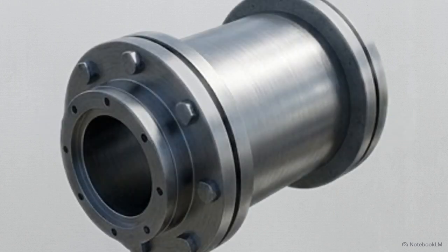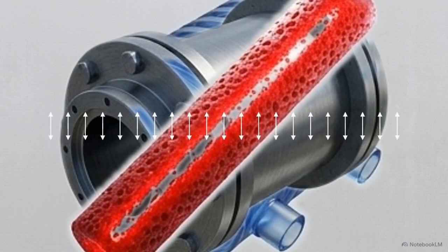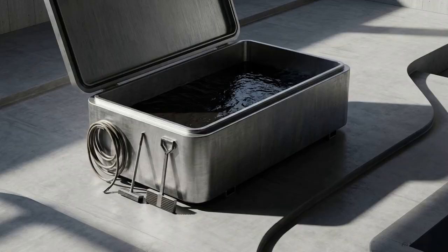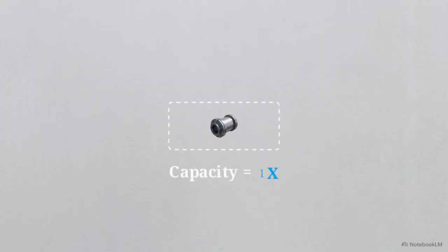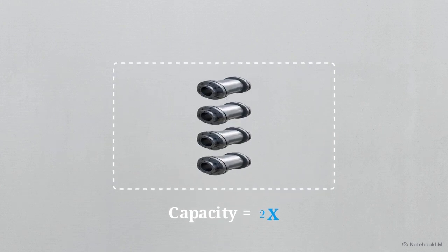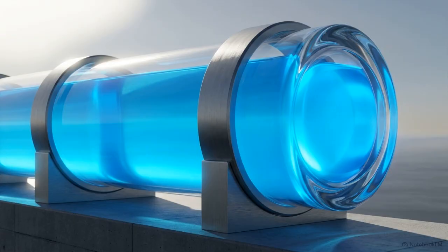The long, narrow shape provides a high surface area to volume ratio, enabling highly efficient heat transfer between the interior reacting fluid and the external jacket. Operating continuously at a steady state guarantees constant output. This bypasses the massive productivity losses associated with the heating, cooling, emptying, and cleaning phases required in sequential batch processing. When it is time to scale up industrial capacity, engineers rarely have to invent new geometry. Output can typically be increased simply by extending the length of the physical tube or by routing multiple identical pipes in parallel. These integrated physical advantages make the PFR an exceptionally powerful tool for continuous production, provided the chemistry behaves perfectly.